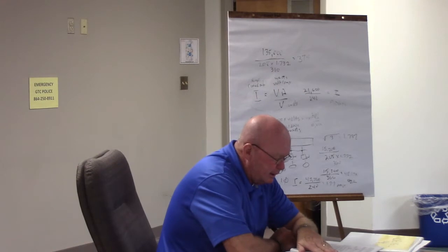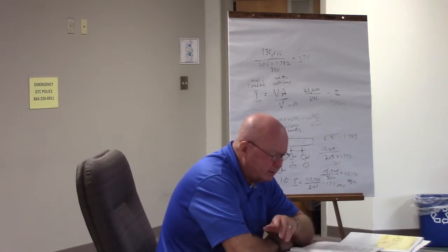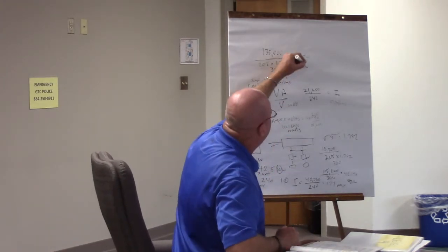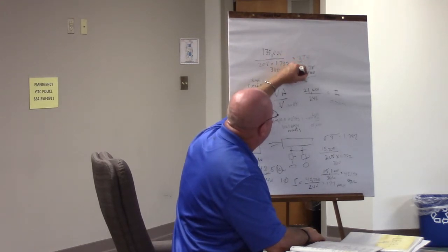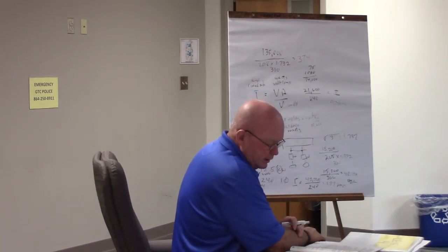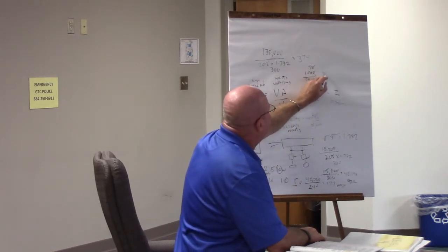Okay. All right. Number 3, what size THWN copper conductors are required to supply the primary of a 75 kVA 3-phase transformer? The primary line-to-line voltage is 480 volts. If you look there, solution says 75 kVA, okay, times 1,000. That's the first thing we have to do. Times 1,000 to give us 75,000. Okay, that's the first thing. Tells us what is their voltage. 480. Yeah, 480.